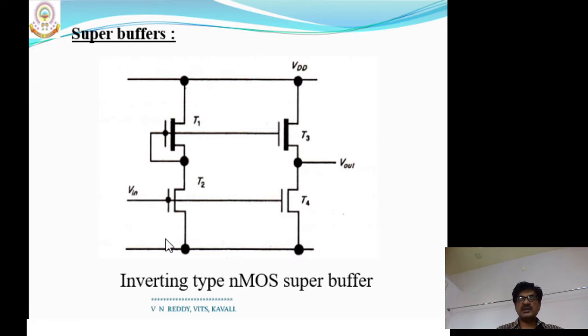So here, in addition to the NMOS inverter transistors T1 and T2, two more transistors are used. They act as a push-pull, named transistor T3, which is a depletion type MOSFET, whereas T4 is an enhancement type MOSFET. See the diagram clearly. Let us see the operation, whether first of all it complements the input value or not.